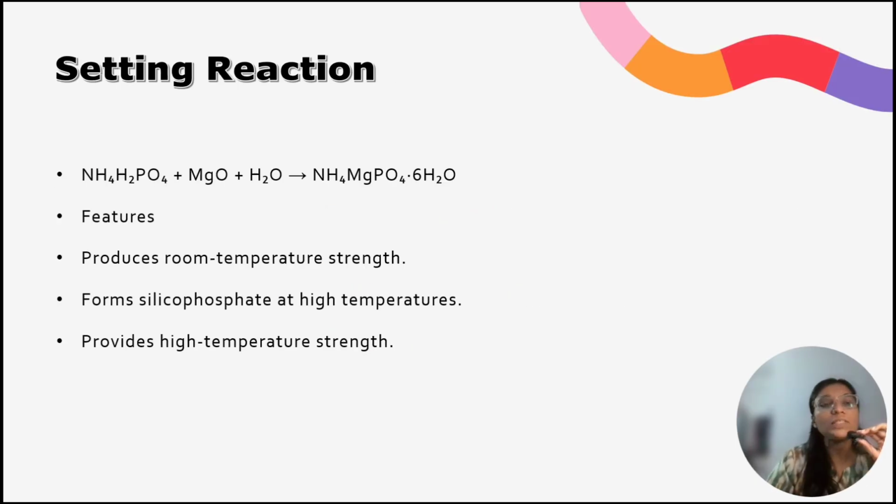So this is the setting reaction. It forms silicophosphate at the higher temperature, and this gives it the higher strength and higher thermal expansion after setting, and also at the room temperature.